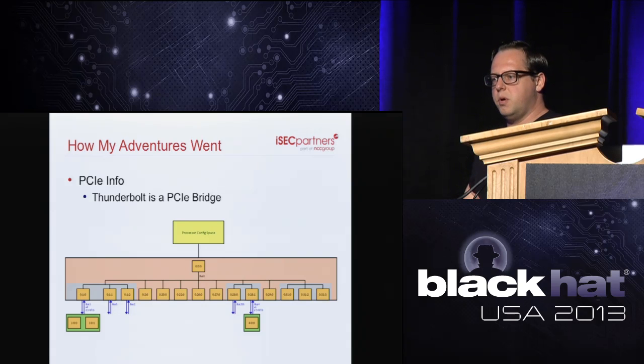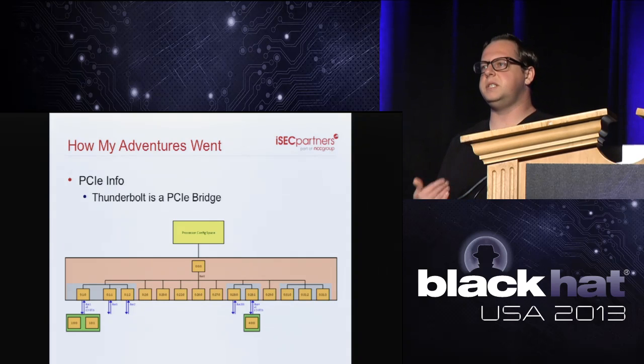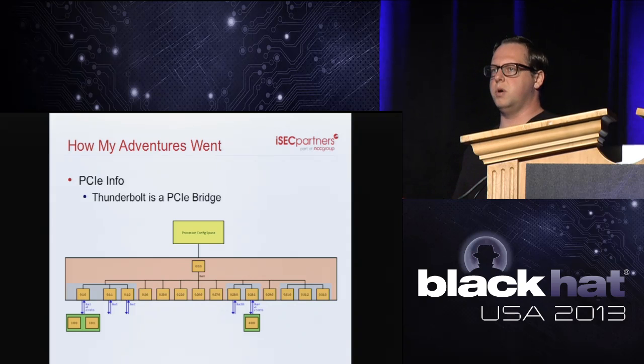Arbor is a paid program for Windows only, but it allows you to see your PCI Express bus and get a lot of detailed information on it, to the point where you can actually pick out problems with your PCI Express bus and implementations of PCI Express devices. So this is an image. If you take an lspci and do the most verbose output, you can take that memory output and put it into Arbor, and you can see other devices' PCI Express fabric.